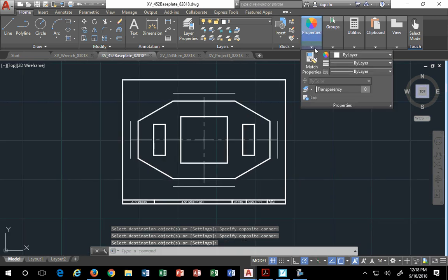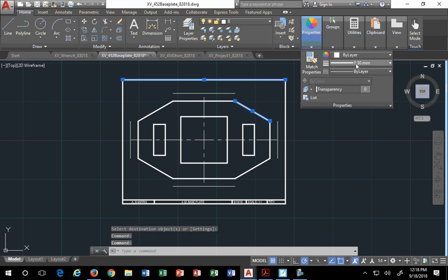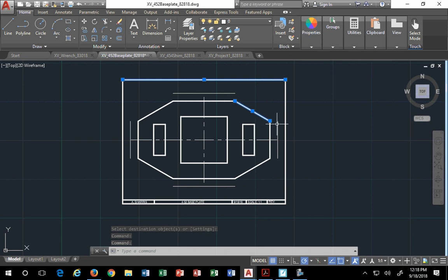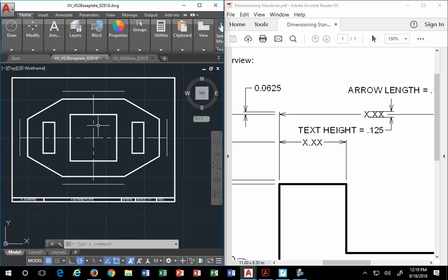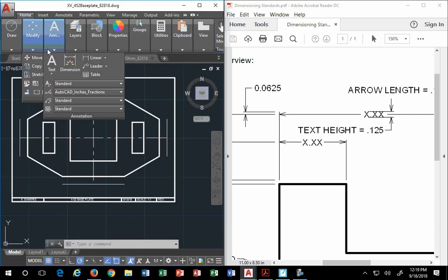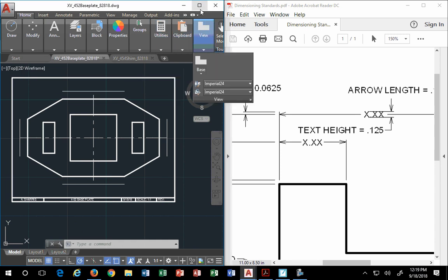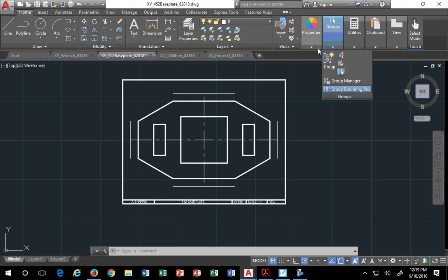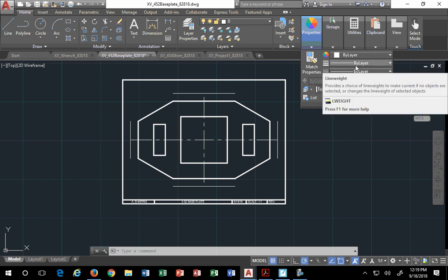So the line weight thickness we're going to use for the border and for our object lines for this class is 0.3 millimeters. Your company can do whatever it wants. I'm just showing what we're doing just so that we can show something. Now, when you drop in your dimensions, I have to maximize this, I can't work like this. Make sure your dimensions' line weight is by layer, and your line type is by layer.